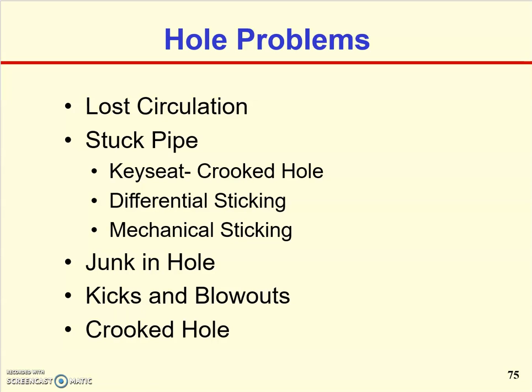Stuck pipe is another problem. It means that our pipe will get stuck in some formations. For example, if you are drilling a directional well or a slanted well that you have to deviate from the vertical direction, then your pipe may get stuck in the formations that are soft, or it may get stuck in the areas that you have drilling fluid, basically stuck with thick drilling fluid attached to the wellbore. So stuck pipe is another problem.